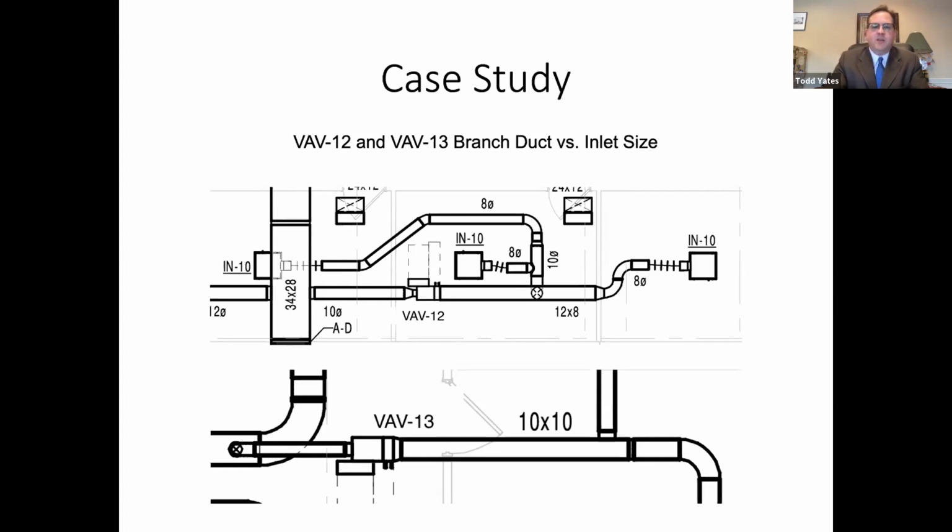So in a way, we stumbled into this. We didn't even understand at first why we were seeing it. These were the VAVs we started on. We wanted a large enough sample to prove what was happening, and we managed to get this VAV 13 in there that had this difference. But so, each had 3 diffusers. The diffusers were similar. The total flow was similar. Everything was similar on these 2 boxes, except for the size of the duct feeding it.